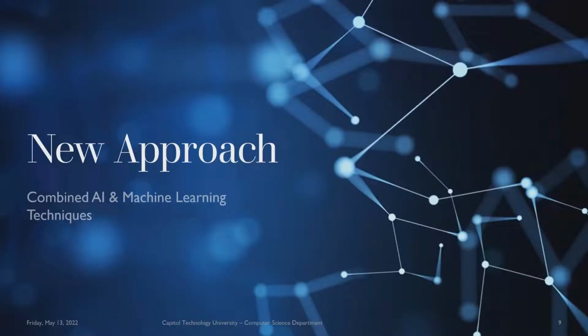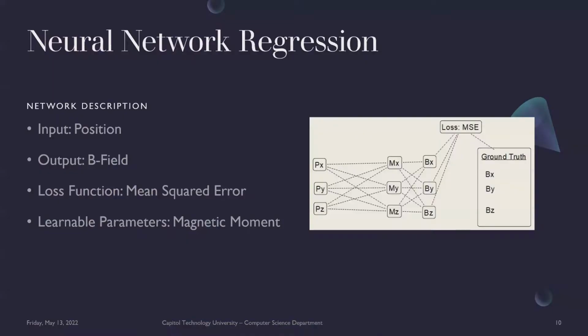The new approach that we are taking to determine the magnetic dipole moment. Techniques applied to machine learning can also be applied to the problem of magnetic dipole moment determination. We can combine the near field measurements of a spacecraft that is rotated about the z-axis with stochastic gradient descent in lieu of Monte Carlo to more quickly determine the effective dipole moment of a spacecraft.